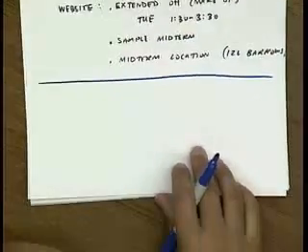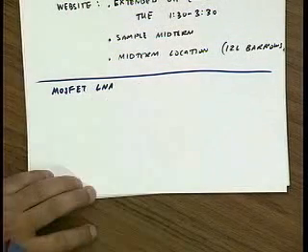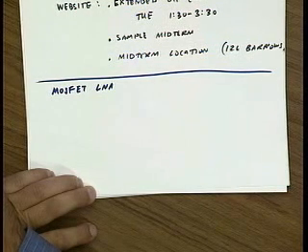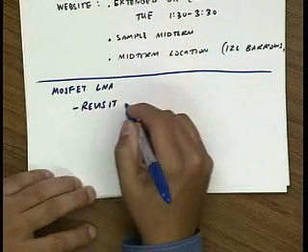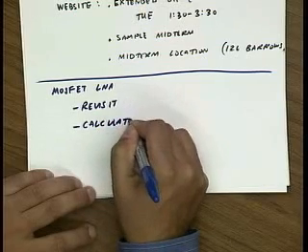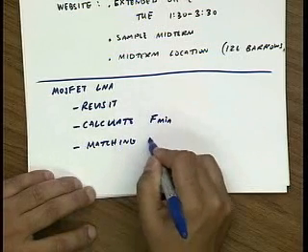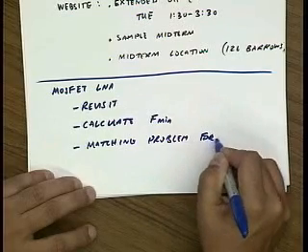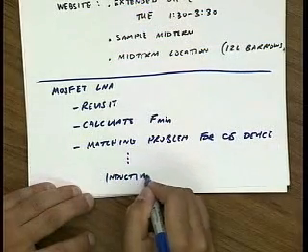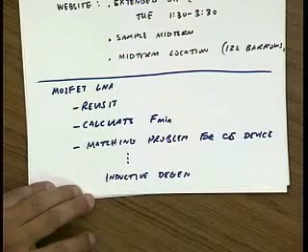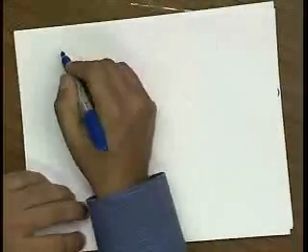All right, so if you remember last lecture, we're looking at the MOSFET device as an LNA. And we basically calculated the noise figure, and what I'd like to do today is revisit that, and in particular, calculate the F-min for the device. And then we're also going to look at the matching problem for a common source device. And then the solution will be to use inductive degeneration. So we'll spend quite a bit of time talking about an inductively degenerated MOS amplifier. Okay? So let's recap the calculation of the noise figure.